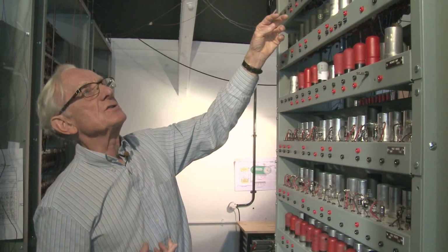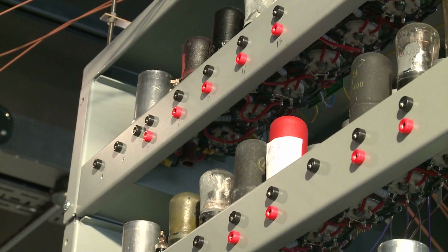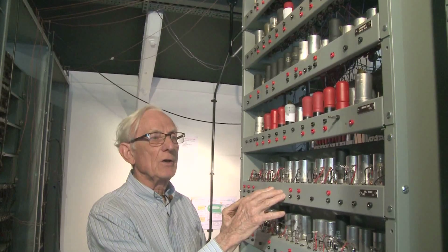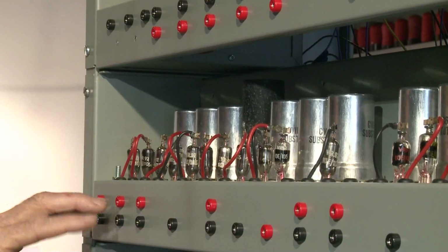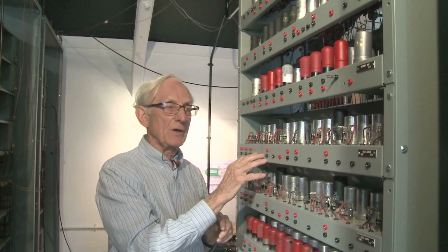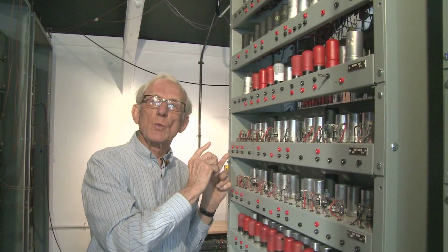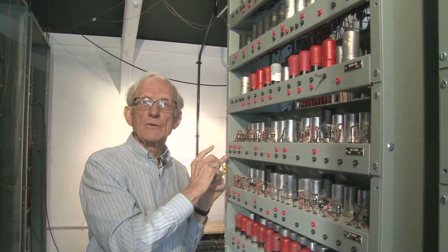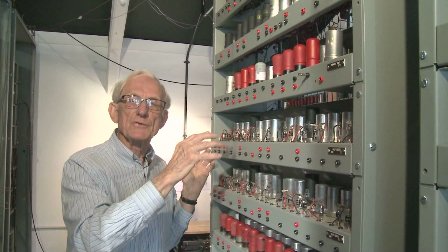The first one is the counter tank, which I think is this one. That's holding an 18-bit number. This is a half adder which the number goes through before going back into the tank. And the point about a half adder is that it's unlike a full adder, it's much simpler because it only has to add a single 1 at the least significant end of a word. It doesn't need to add 2 long numbers together.